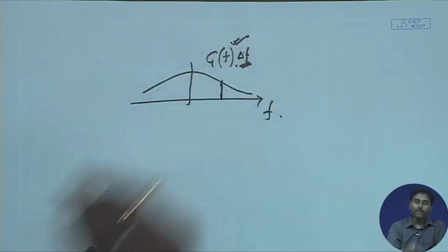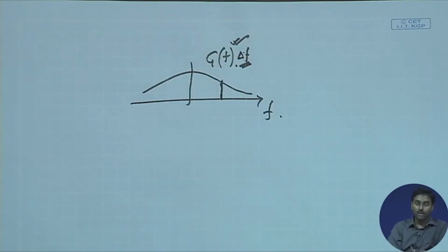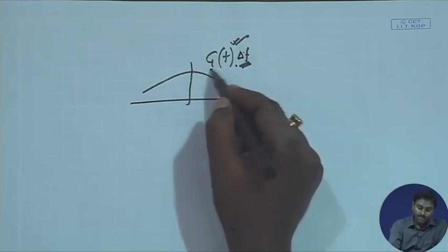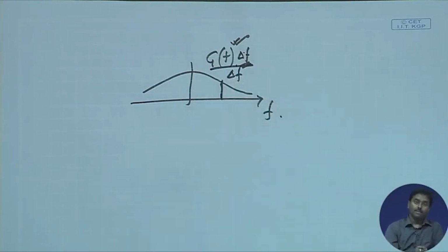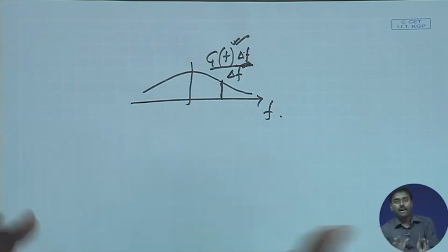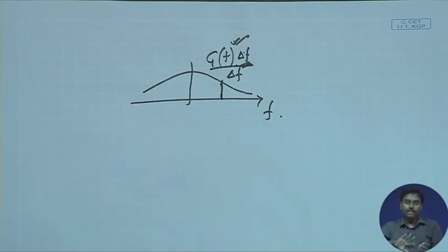So, basically the spectral strength will still become 0, whereas what we get is that spectral strength divided by del f, that means spectral density per unit frequency, how much it has, that is something that we get. Okay. So, GF defines that. So, that is where these two particular spectrum has slight differences, and you have to be very careful when you are generally talking about these things.